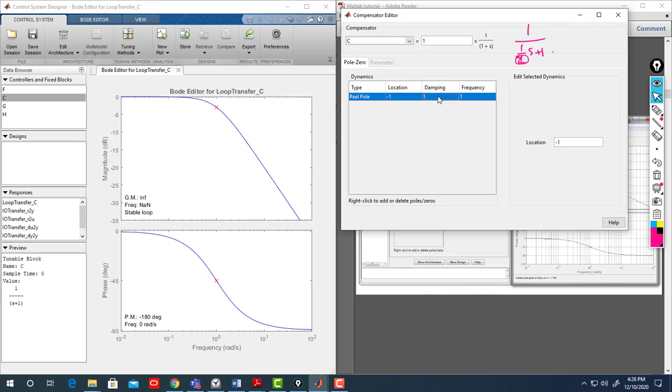Because this is a first order system. It's like a real system. Assuming you have a second order system with two poles located at the same point, your system is critically damped, which means the damping ratio equals 1. That's how it is here. At the end, you are adding a real pole in this experiment.